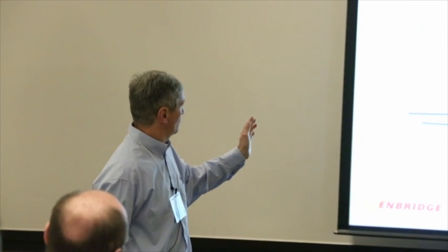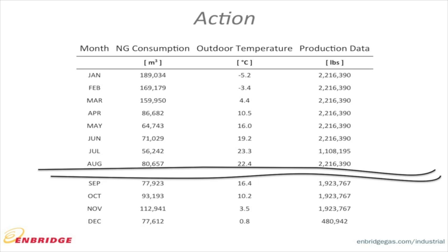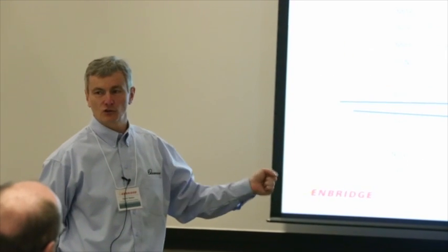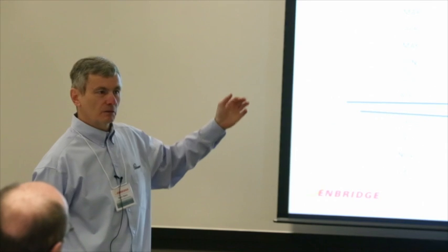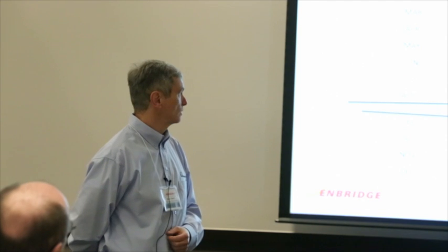This is the same as what we had before: months over 3 years, natural gas consumption on a monthly basis, outdoor temperature, and I added production data in there. Because usually in an industrial environment, without putting production data there, you're really not doing energy assessment, no energy analysis. Because production is what drives your energy costs and the reason why you use energy in the first place.